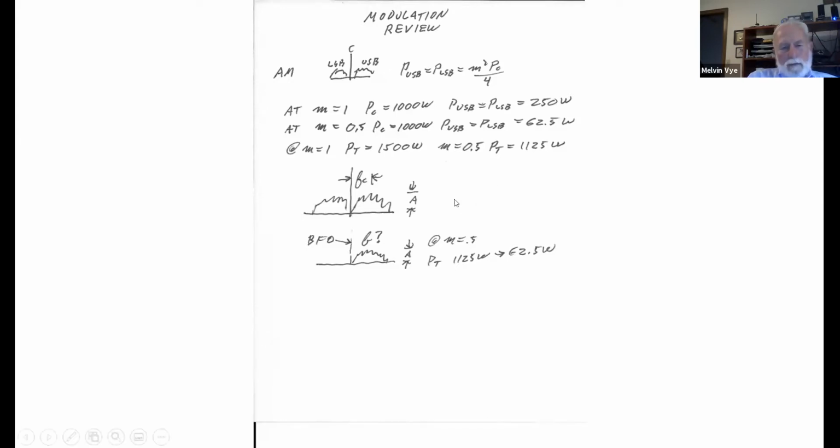All right, frequency domain. What comes out of the speaker of the receiver is represented by the amplitude of whatever is in these sidebands. And the sidebands are mirror images of each other, so each one contains all the information that you need. And the frequency that comes out of the speaker is the difference between the frequency of what's in the sideband and the carrier that you transmit. But it takes a lot of power.